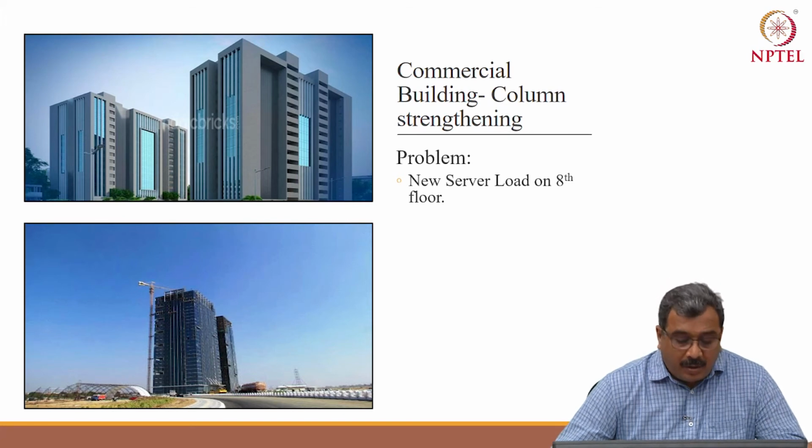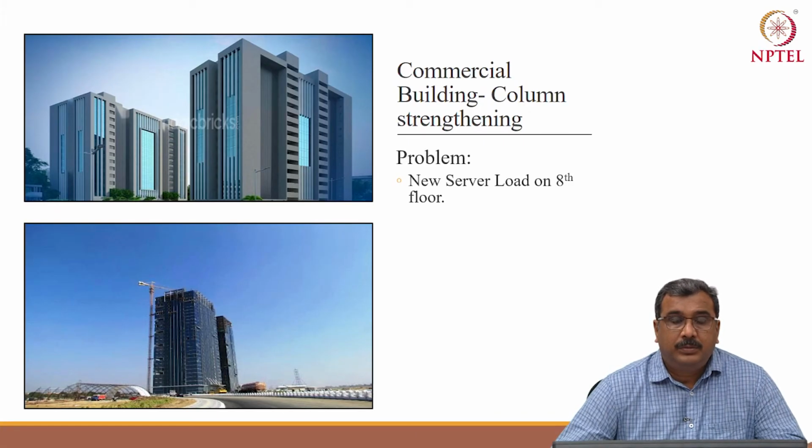So, considering the new load, a whole structural analysis has been carried out, and it was found that the 4th, 5th and 6th floor columns, a few of the columns of these 3 floors, were not adequate, and were found to be deficient for moments. Axially, for compression and for shear, they were safe. As I told you, the 8th floor was not constructed.